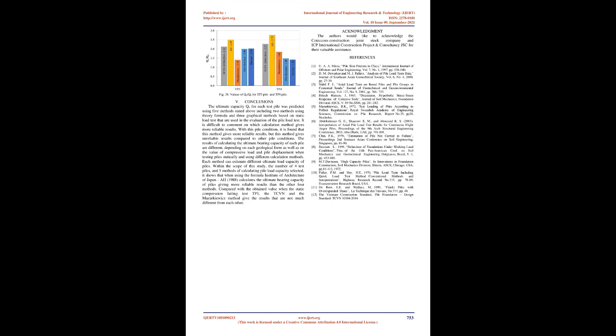Conclusions. The ultimate capacity Qu for each test pile was predicted using 5 methods stated above, including 2 methods using theory formula and 3 graphical methods based on static load test that are used in the evaluation of the pile load test. It is difficult to comment on which calculation method gives more reliable results.